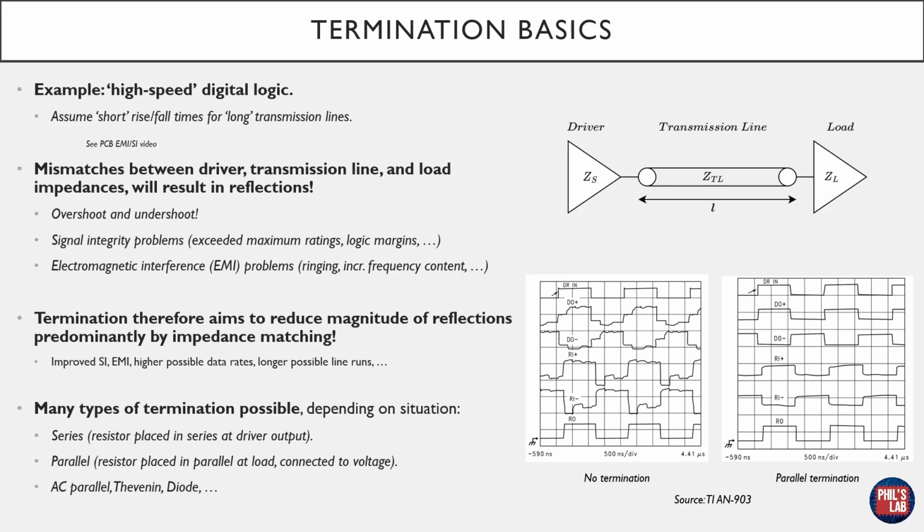This could be volts of overshoot and undershoot in certain cases. This then leads to signal integrity problems. We might exceed maximum ratings of the input ratings, we might exceed logic margins if we have too much undershoot, and generally our signals will be very distorted. In addition, reflections and improper matching of impedances can also impact the EMI performance of our system, which means ringing, increased frequency content, and so forth.